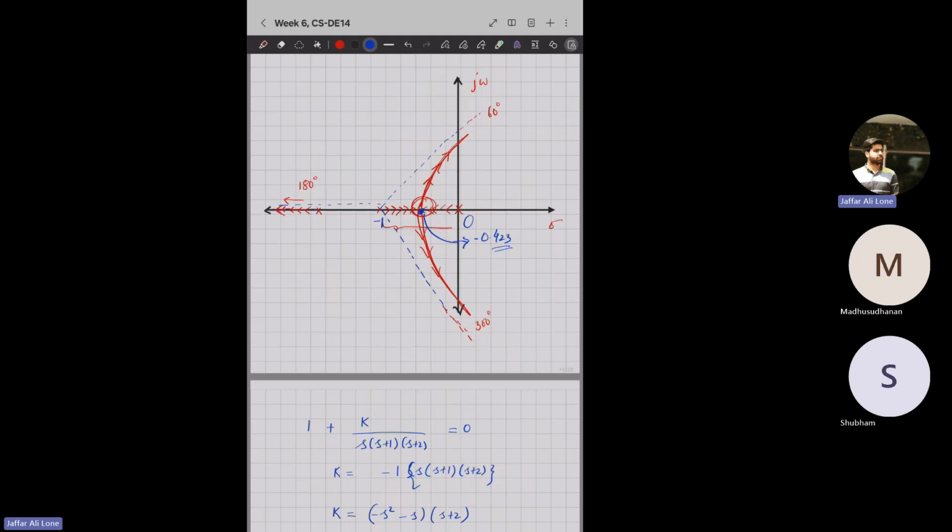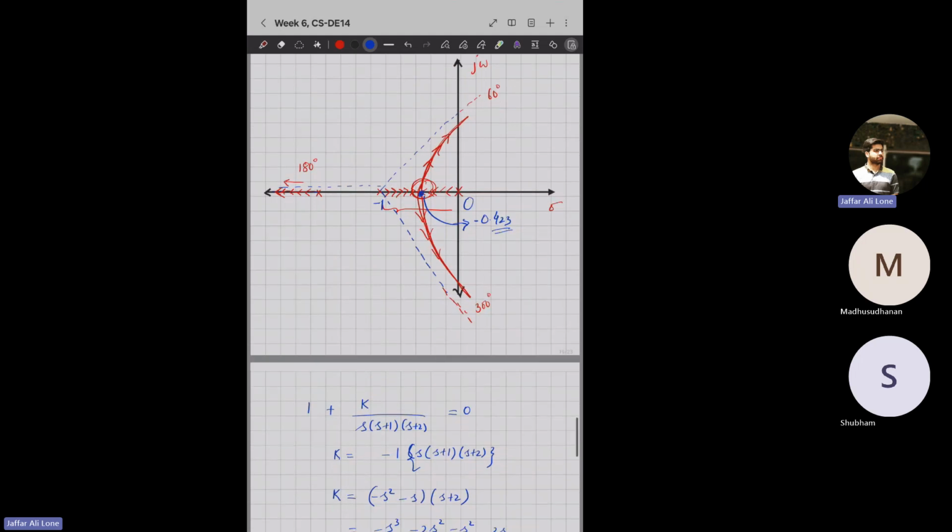And we will also be doing, I don't know whether that is in the syllabus or not, control design by root locus, because we are actually varying k. From this root locus, we can stop at that value of k where we are getting less overshoot, more rise time, or whatever is the design specification. When we traverse through the root locus, we can stop at the point where we are getting the desired specifications. So that will also be a topic for another day.